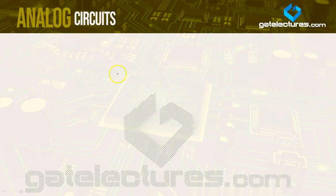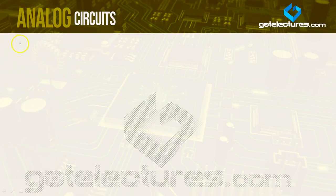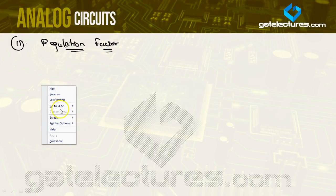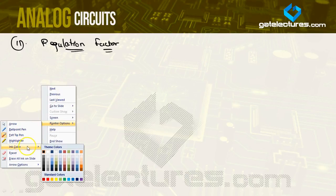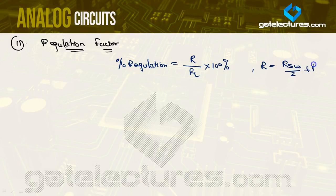Now the next one is the regulation factor. We define the regulation factor as VDC-NL minus VDC-FL upon VDC-FL. The expression will remain the same, so the percentage regulation will be equal to R upon RL into 100%. The only difference is that R is equal to RSW by 2 plus RF. This is the percentage regulation.